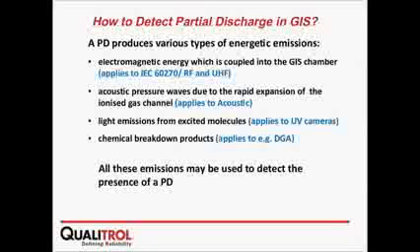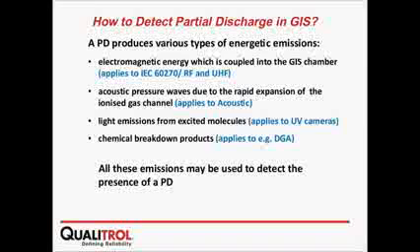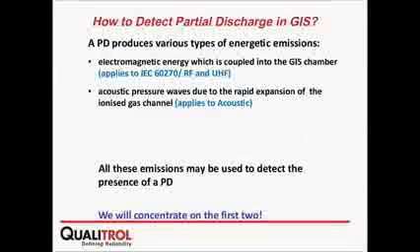So all those methods are able to detect partial discharge, but the really effective ones that are used nowadays are the electromagnetic with the UHF and the acoustic pressure. So we will concentrate on the first two.